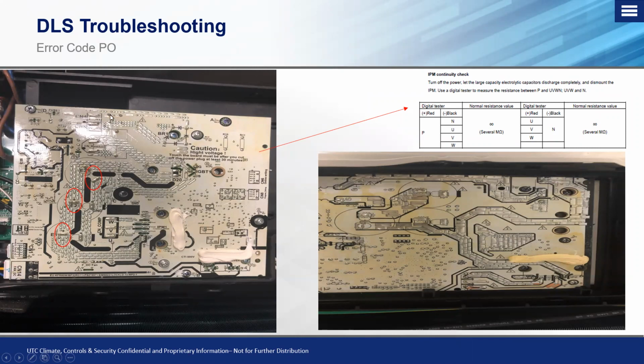Now, one thing we can troubleshoot is, okay, I have the correct power in, but am I getting the correct power out for DC voltage? The capacitor buses, because that's going to be next in line aside from the reactor on there, which we know is that filter, which essentially cleans up that newly generated DC power. Okay, so what you can do is verify your incoming AC voltage, of course, plus or minus 10%,